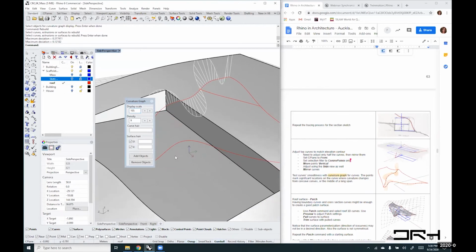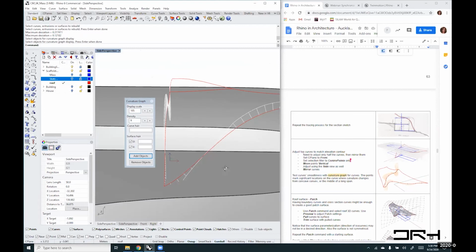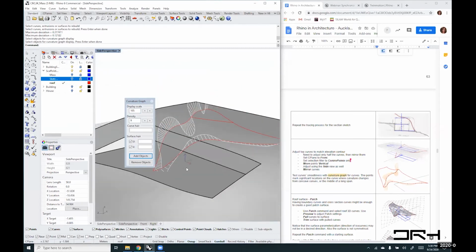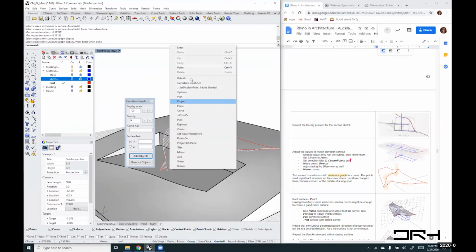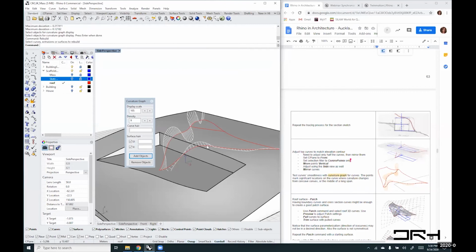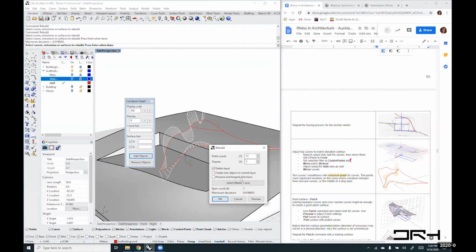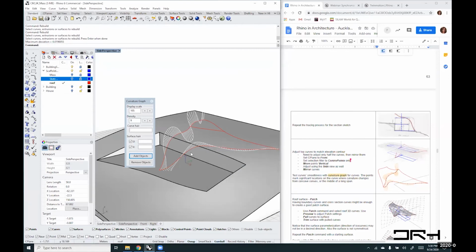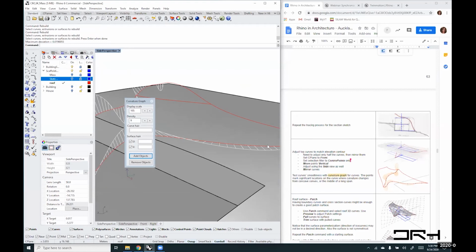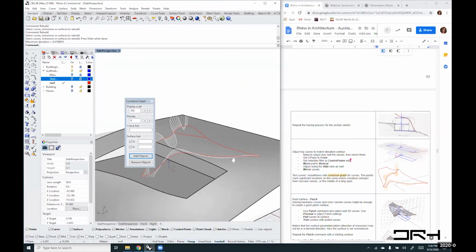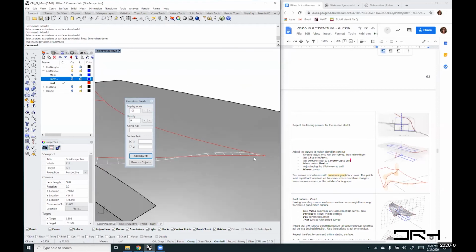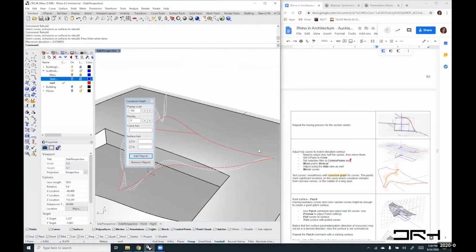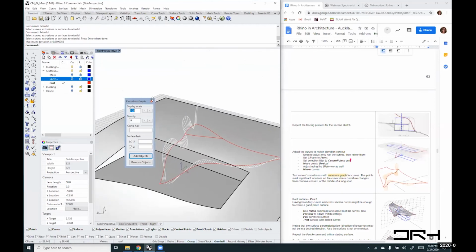I can check the add object here and add this curve to also look at it and see how it looks. And I perhaps can also rebuild this curve to be degree 5. Okay. And again, it looks a little bit smoother. So if you don't use degree 3, use degree 5, and this works well with NURBS curves. Don't use degree 4. And those curves look good here.